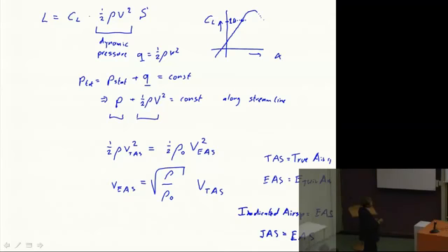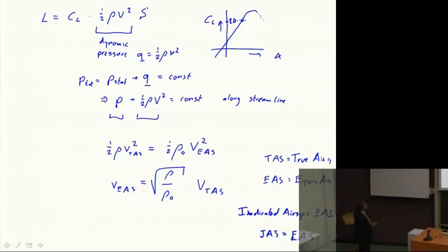So that's the real meaning of CL, and we need to know that we can just regard this as the lift force, but then without dimensions, because if you calculate the dimensions of all of this, you already get newtons. So it has no units, which is not very strange, because it captures a shape, and that doesn't have any units. So if you put in kilograms per cubic meter, meter per second squared, and squared meters here, you would get kilogram times meter per second squared, which is the same as Newton. So if we talk about a dimensionless lift force, we talk about the CL. And that's what we will use in the second hour to calculate in our stability calculation.